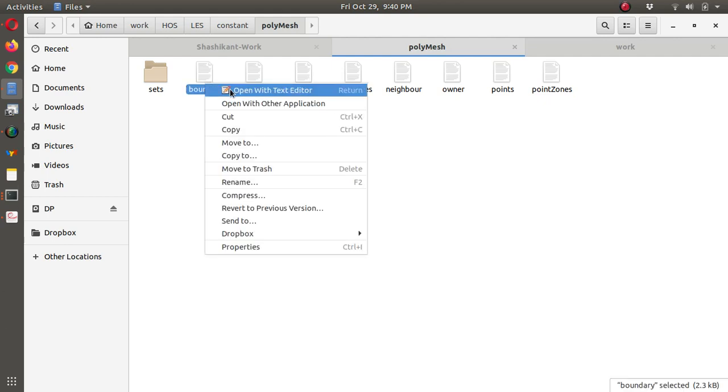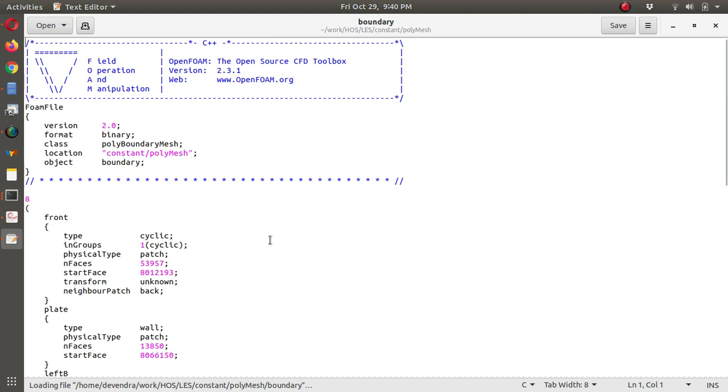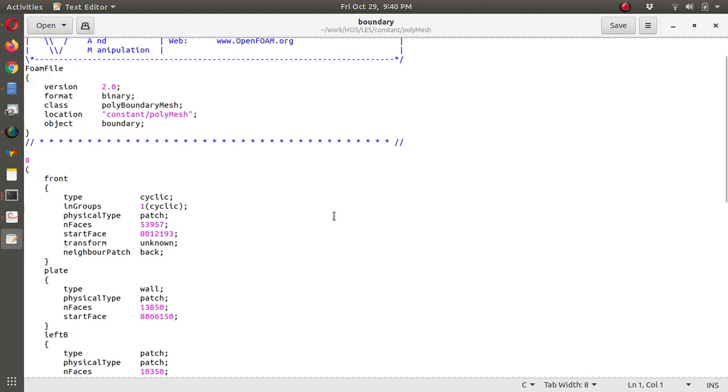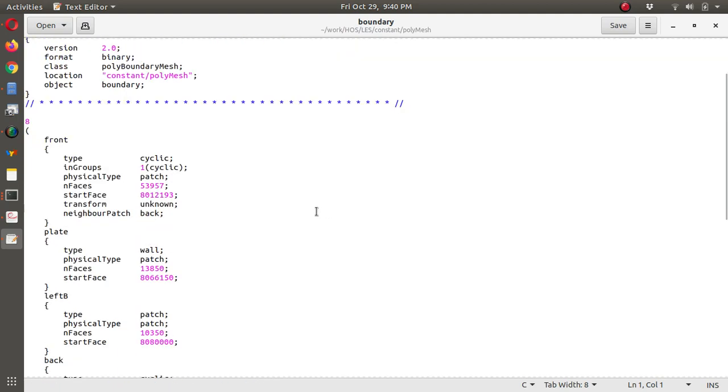As per my requirement, I have renamed the boundary conditions and I have given some more information, like I need the front face which will be kind of open to atmosphere, but as we have considered it is a slot jet, that means a very long nozzle is there which is providing a slot jet to the flat plate.